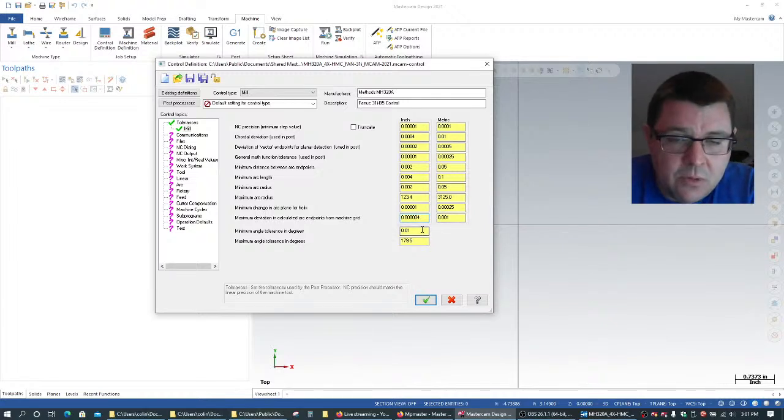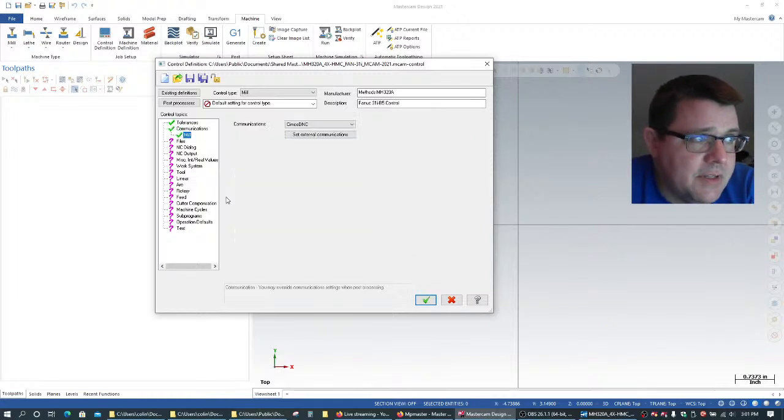Depending on the input increment, you may be able to adjust this, but keep in mind you want this to be nice and accurate. So I'm also going to do, 1 micron here is 40 millionths, so I'm going to do 1/10 of a micron, which is 4 millionths. So now these values match each other. So I've set up my tolerances.